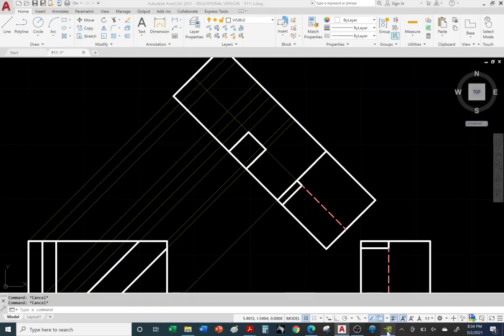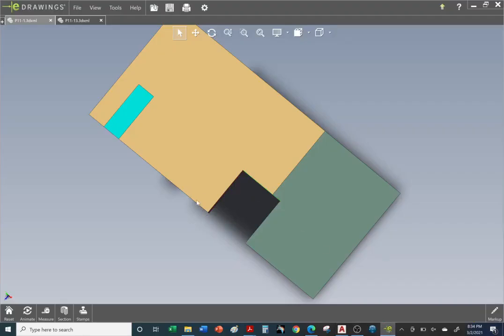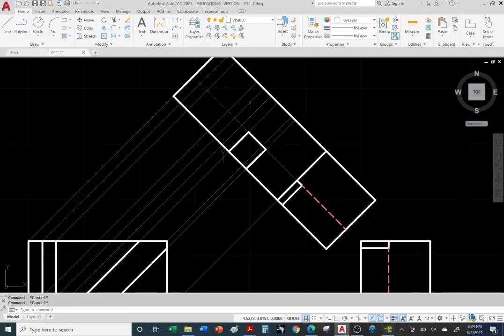Okay, so we're not quite there yet. See how it's open here? So we need to break this into two separate object lines. So let's go back. Okay, so this line we need to adjust. Let's go ahead and shorten it to the correct length because there's an opening here. Escape to deselect, and we'll just create a new object line from this vertex to this one, and right click enter. Okay, so there's the slot, and the whole purpose of this is so we can get a clear picture and dimension it, but we're not dimensioning yet, at least not in this chapter.